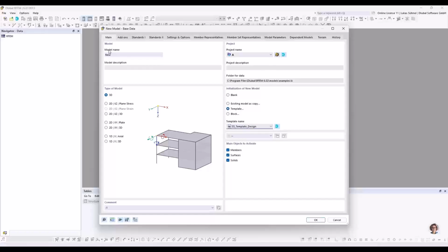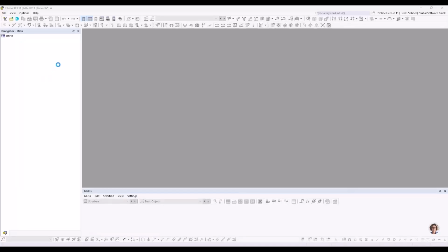So basically you create an empty file in which the information from that template file will be imported. Let me show that as well. And as a result, your file is not empty anymore. You get these load combinations, the protocols, maybe even materials and cross sections, whatever comes to your mind that you want to have as a default in a new file can be saved in a template, and that will be imported afterwards. Takes a moment.